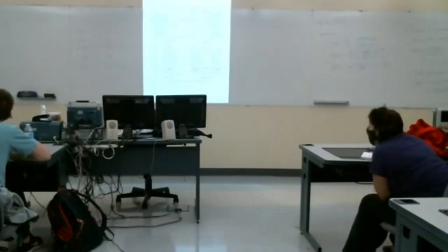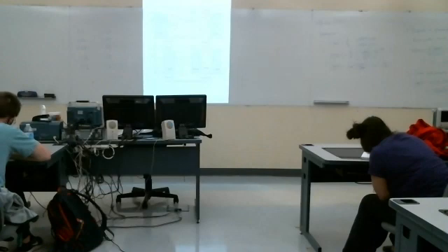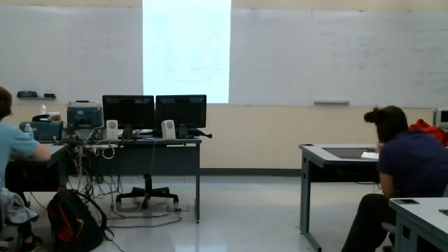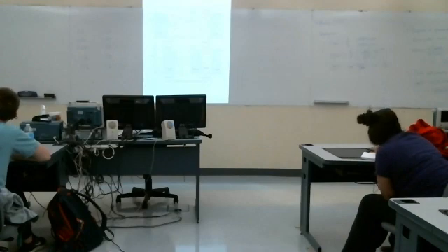Of course, this is 20 log of 1 plus omega over omega c squared, to the 1/2, right? That's what that looks like. Now, to a pretty good approximation what that term looks like, we'll do this on log paper.